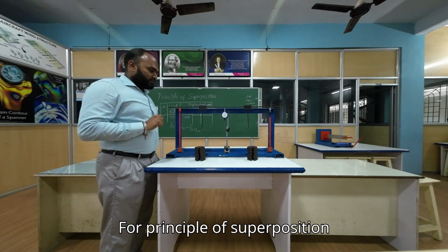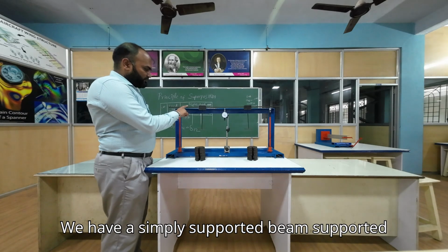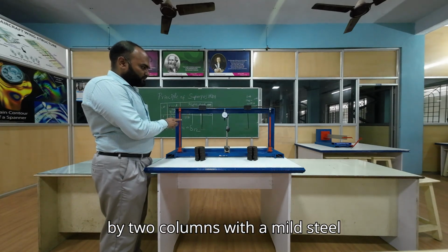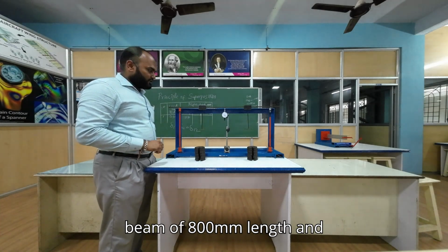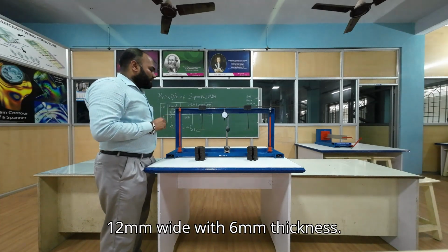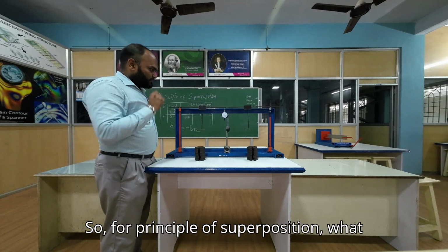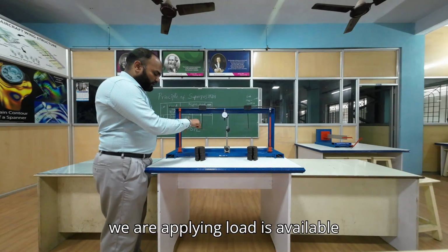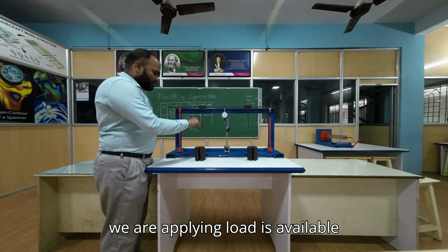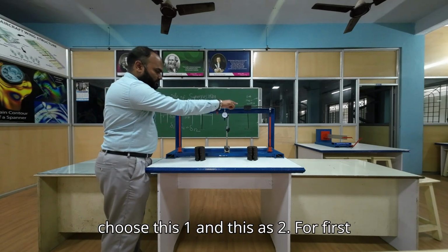For principle of superposition experiments, we have the beam setup. We have a simply supported beam supported by 2 columns with a mild steel beam of 800 mm length and 12 mm wide with 6 mm thickness. So for principle of superposition, what we have here is the point where we are applying load is available here. So there are 2 points. So we choose this one as 1 and this as 2.